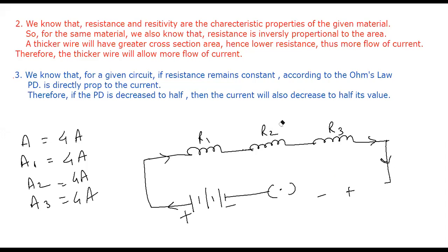What is the conclusion that I draw from this? What is the conclusion, children? Equal current is passed through all circuits. In a series circuit, the current will remain constant. When the resistances are connected in series, it does not make any difference to the current. Current remains the same at each and every point. You connect it here, here, anywhere, it shows the same value. Correct?